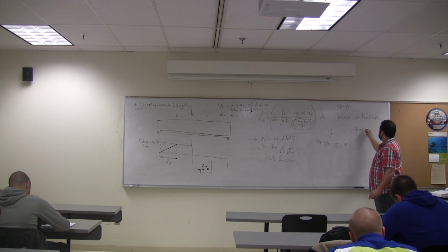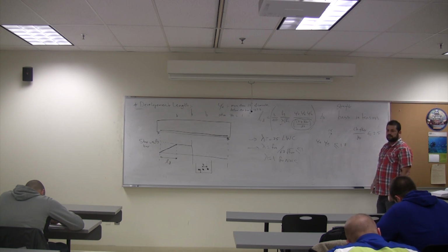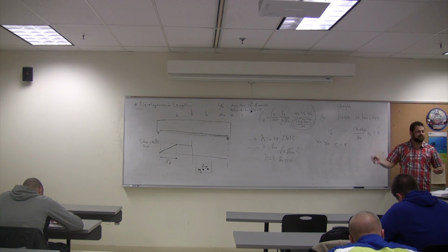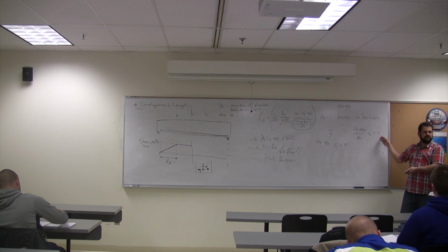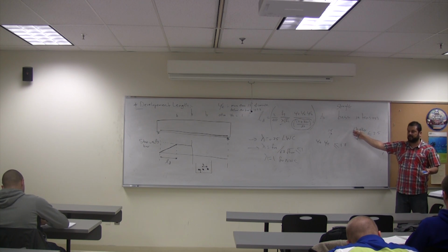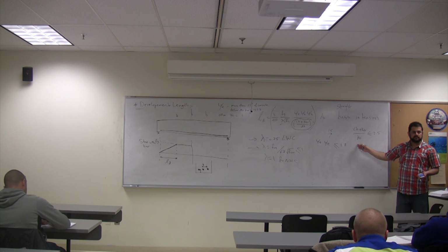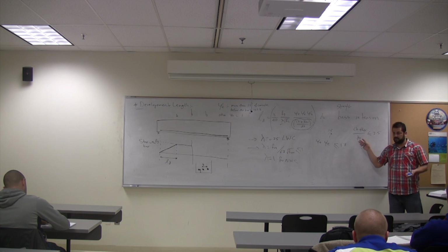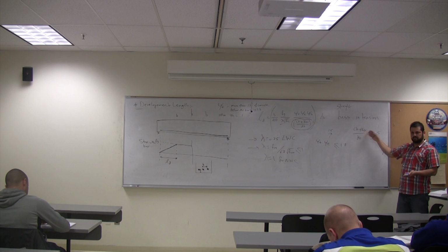CB plus KTR over DB is less than or equal to 2.5. That's why sometimes you spend a lot of time and effort calculating KTR and making a lot of assumptions, and at the end, CB by itself is going to exceed this limit. So you go back to this limit. If you have a cover of 2 inch, that's a typical cover, for number 7 bars, 2 divided by 7/8, so you are almost there. For number 8 bar, you have 2, which is fine.